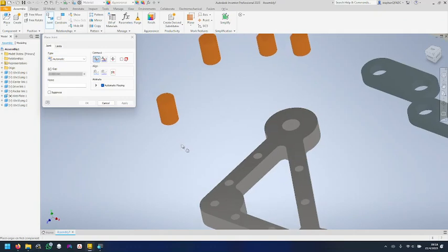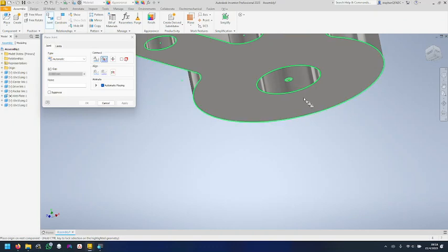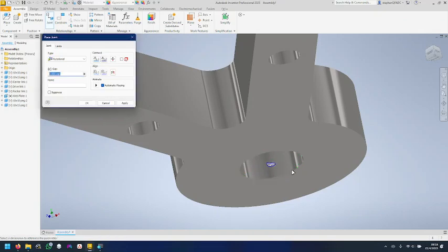this case. So the first object I select, that's the one I want to move. So I'll select there. I want that cylindrical face there. And then when I select here, I'm not selecting this object as a cylinder like this, right? I want to come down until it's selecting as a face like this. Then I'll click. Then it'll move, right? You can see it rotates like that. It does that little animation.